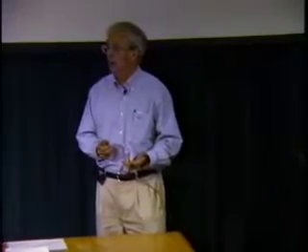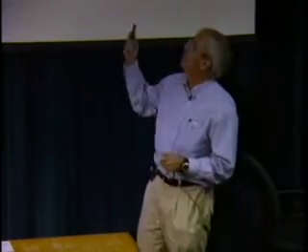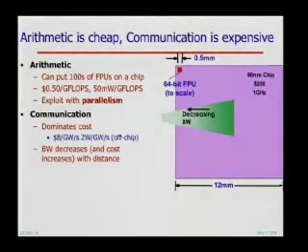But also notice that if you want to get performance out of this chip, you don't do it the way things used to be, where you build a more powerful processor by building a multiplier that could operate in fewer cycles, or putting more of your floating point unit combinationally rather than sequentially on the chip. Today, this is a fully pipelined floating point unit that can start a multiply and an add every cycle. You've already done all of that, and you can still put 400 of them on a chip. So it's clear that if you want a higher performance machine, that performance comes from parallelism. The reason why you don't get 50 cents and 50 milliwatts per gigaflops is that the communication dominates the arithmetic entirely.